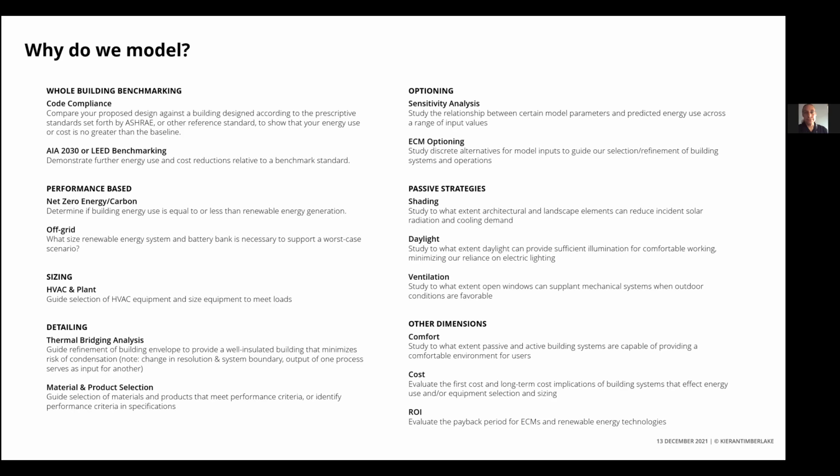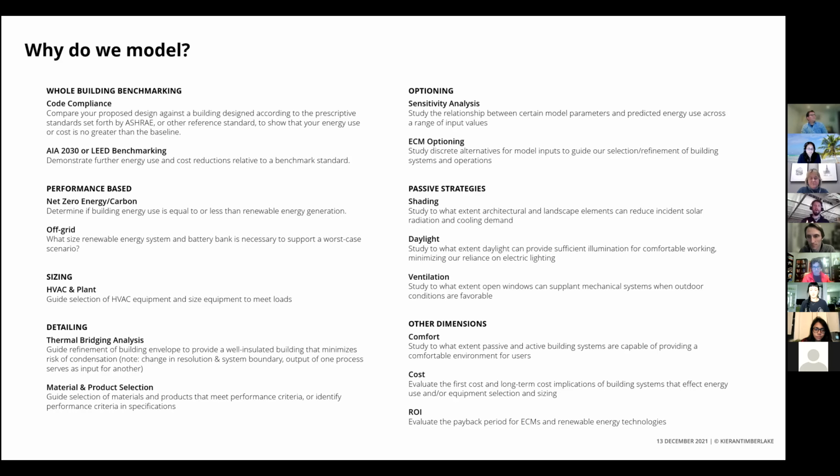So each one of these questions, whenever we ask them on a project, requires different processes and different levels of detail. So for example, that whole building compliance benchmarking may rely on ASHRAE default values, populating the model with all these default values. And we're simply benchmarking against that baseline and showing maybe percent reduction in energy costs for LEED or percent energy use reduction for code.